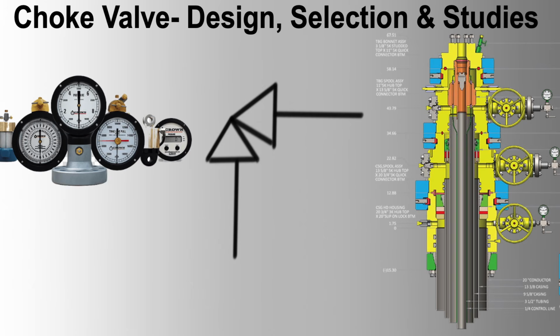2. Seal design. Leak prevention. Ensure seals are designed to prevent leaks under high pressure. Material durability. Choose seal materials that can withstand the specific operating environment without degrading.